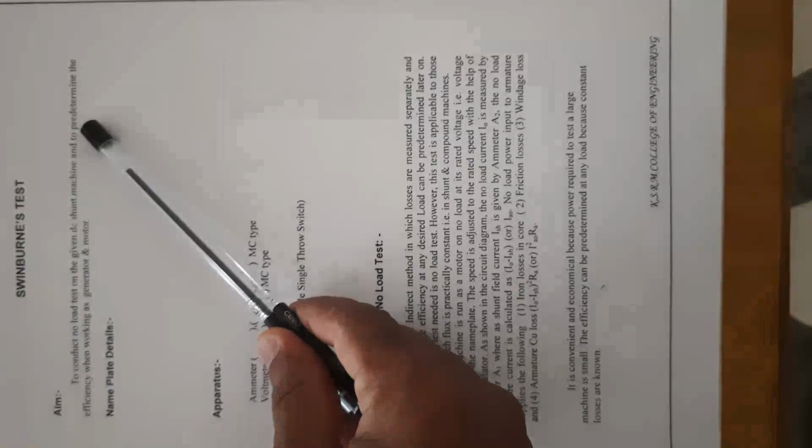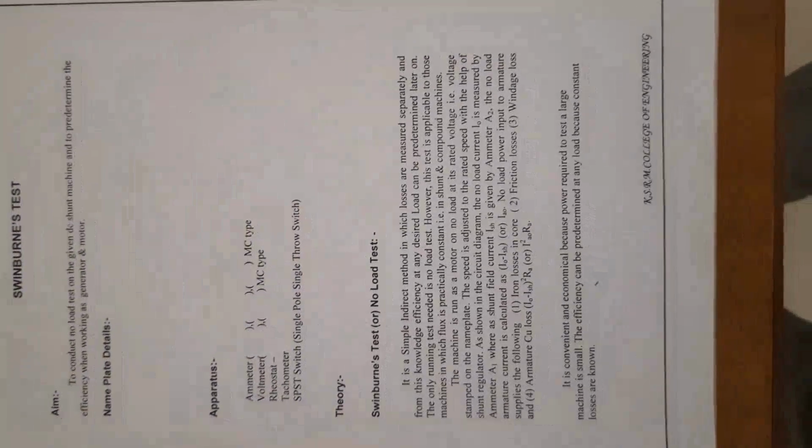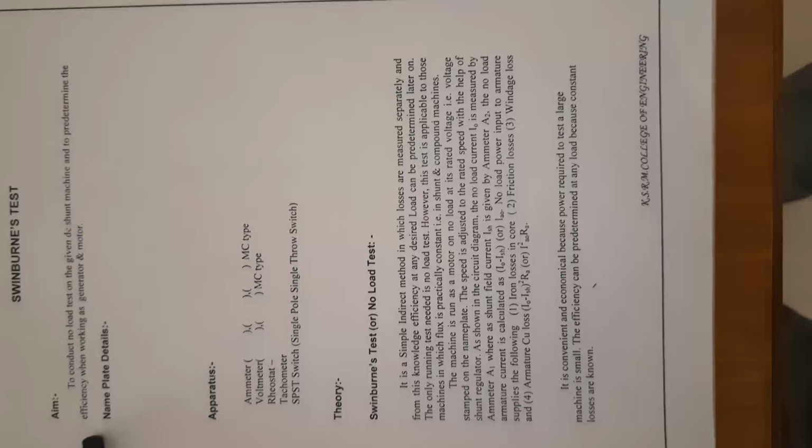Good morning, students. In today's session, we will see how to conduct Swinburne test on DC shunt machine. The purpose of conducting Swinburne test on DC shunt machine is to estimate the constant losses, and with the help of the constant losses, we are able to predetermine the efficiency of the shunt machine when it is going to act like a generator and when it is going to act like a motor.